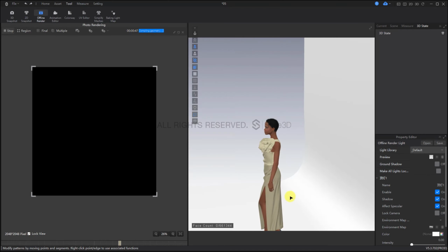Okay, so let's talk about how lighting works. First we open up a new project and use a simple sphere to demonstrate. Open up the props in the scene. Find a sphere and import it into the software. Then we'll use the rectangle tool. Create a rectangle in Style3D with a height and a width of 150 centimeters. Lay the rectangle flat on the ground.